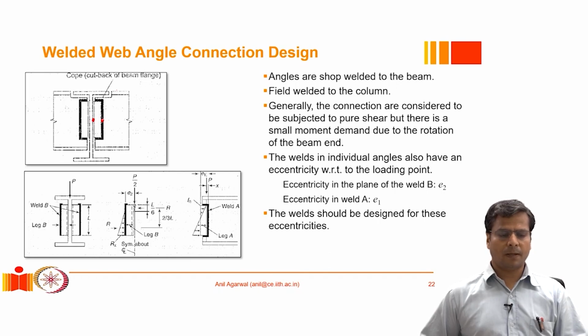Now, if we say that one of these locations is fully pinned, then what we are saying is that this much shear has to be resisted by this flange, by this girder, and over here this weld is pinned, but over here it is getting some reaction from here. So basically, when we design this weld on the right hand side, we have to consider this eccentricity.